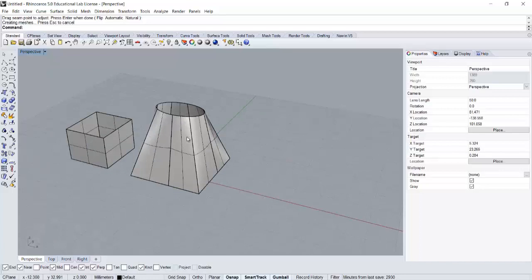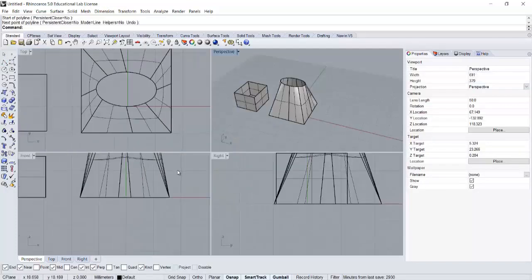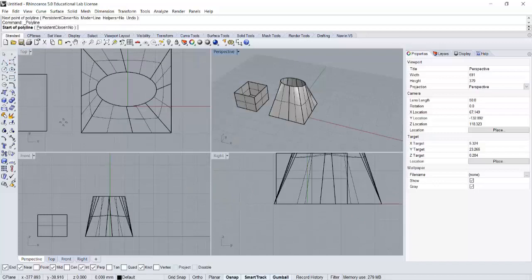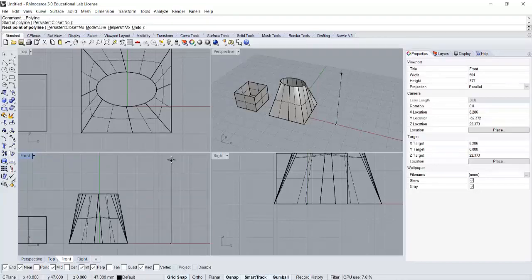So I've had extrusion, we've got loft. Let's do a rotate now. So if I draw a line, actually I'm going to draw this from the side. So I'm going to draw a vertical line. Let's put grid snap on to keep it neat. Do a line like that. You can see in the 3D window how that went vertically because I'm drawing in this front view.